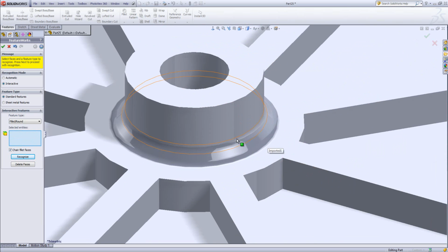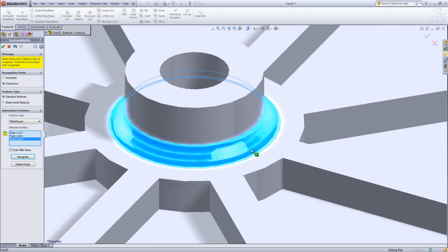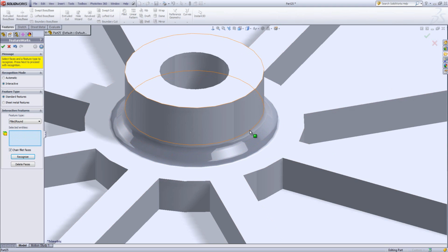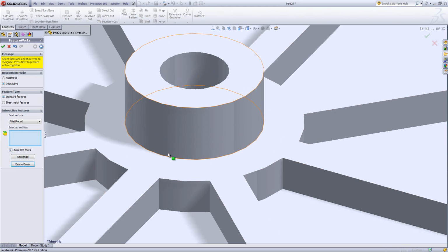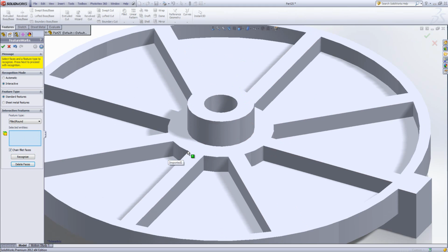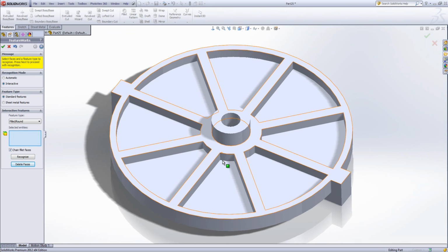Okay, in certain areas of the design, you'll see areas like this one, where it's not entirely clear what's going on here. It could be a chamfer in some areas or fillet in others. You could try and analyze and work out which areas are which and pick those up from the model. But sometimes FeatureWorks can struggle with complex areas where you've got items overlapping or intersecting with each other. What we can do in certain areas like this one is to actually just delete these faces to remove them from the model. It means that then you can just reinsert those later on. And it helps just to take them out of the design and then allow you to actually get something out of the model for the features underneath.